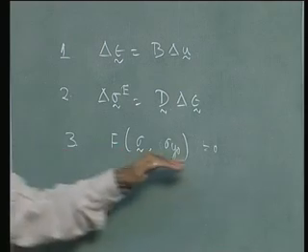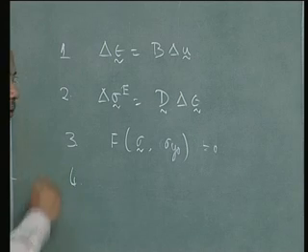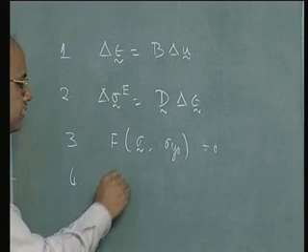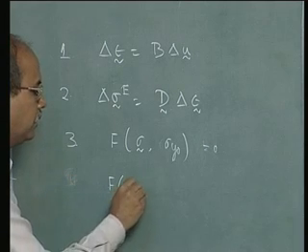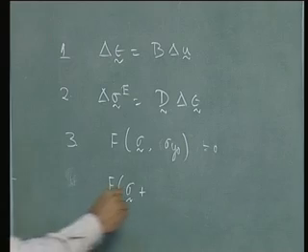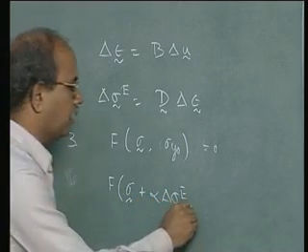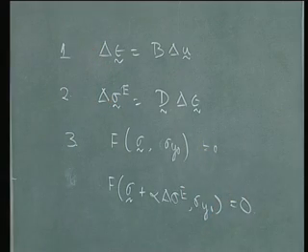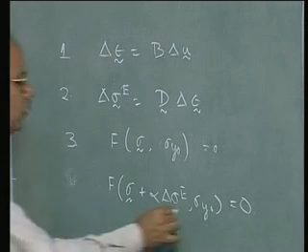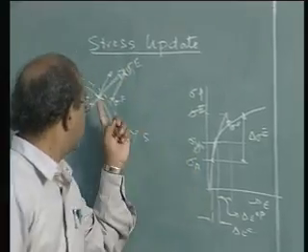Now this is what I'm going to solve. How do I do that? Quite simple. I'm going to restate this as a function of sigma plus alpha times delta sigma e, comma sigma y0, which should be equal to 0, in order that I calculate this contact point. So this is what will give me the contact point. That is this point here.